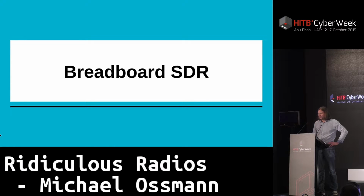And so what I came up with is a little circuit that I call my Breadboard SDR. And I've had thoughts about making more Breadboard SDR projects, but this is the first one. And it's the simplest radio receiver that I've been able to devise that uses a general purpose microcontroller and that can receive radio signals that are much higher frequency than the speed of the analog to digital converter. The analog to digital converter on a typical microcontroller only operates at a few 100,000 samples per second, or maybe a few million samples per second.